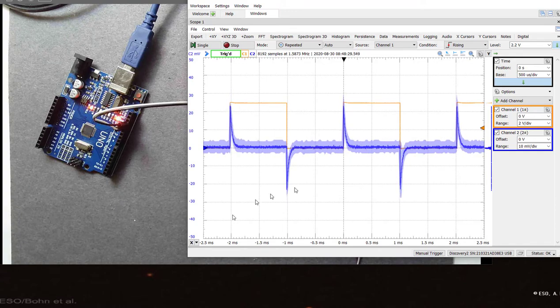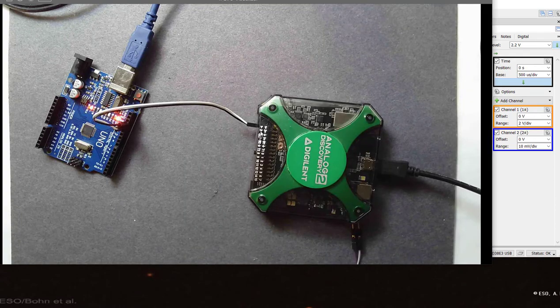Anything we do to the interconnects, anything we do to increase the coupling between the wires of channel 2 and channel 1 is only going to add to that capacitive coupling. That's capacitive coupling. Now let's look at the inductive coupling. And the way we do that is we're going to add another pair of wires to channel 2 and we're going to short the ends. So the input will be shorted and we'll try to keep that loop far away from the aggressor loop.